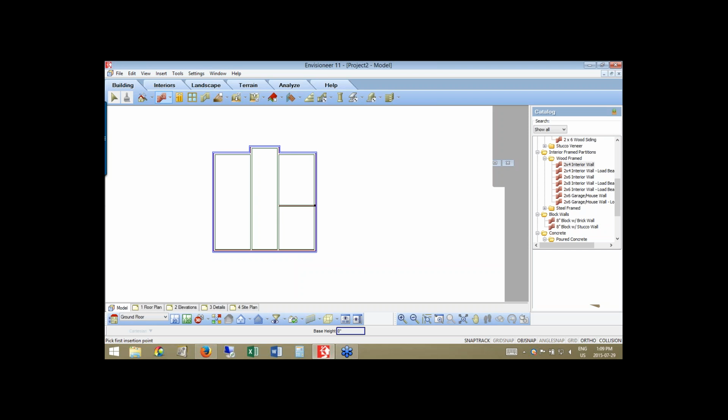Okay, we'll do that one more time just so we're sure everybody understands the offset tool, because it's very handy in your designs. Right click, Enter Insertion Offset. The Enter Insertion Offset dialog box pops up, wants to know the distance you want to be away from a corner. I'm going to tell it this time 12 feet. I click OK. Now any wall that I put my cursor along will show me the 12-foot distance.